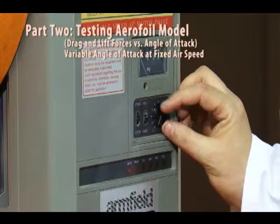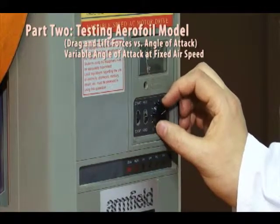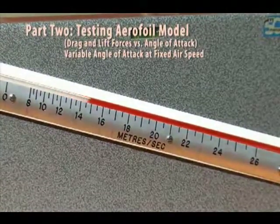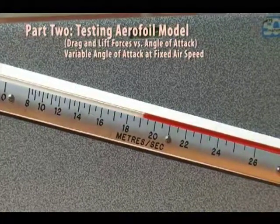Run the motor fan at a constant speed for all runs. Set the airspeed at a certain value on the manometer and don't lower the speed to zero at the end of each run. You can simply turn the motor fan off and on to get back to the same airspeed.